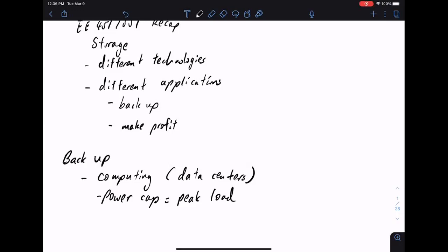How about the energy capacity? So how long should the battery operate? Let's say the power fails and your battery kicks in. How long do you think the battery should go? Okay, so I have a 10 megawatt data center. My battery is 10 megawatts. The power fails and the battery takes over. But there's a finite amount of energy, right? Energy is power times time. So what is the amount of energy I should have in my battery, or how should I size a battery?